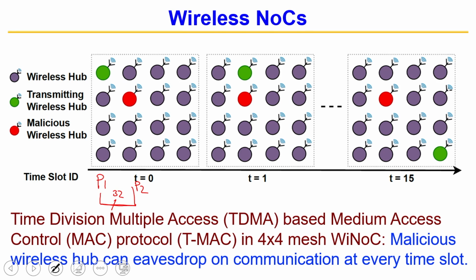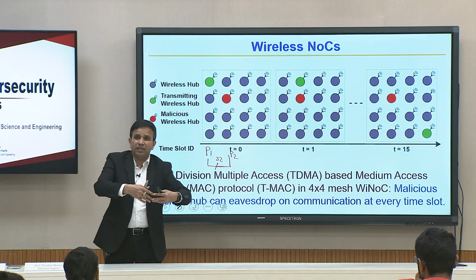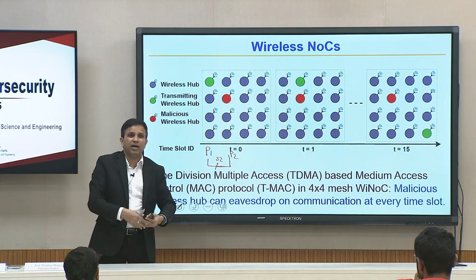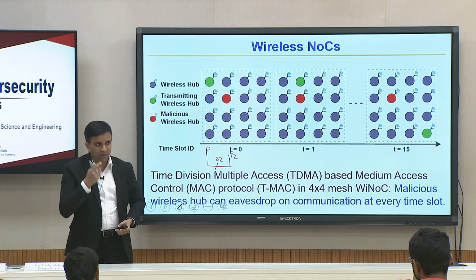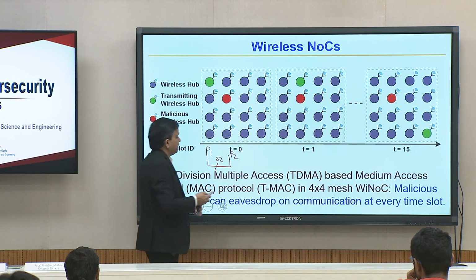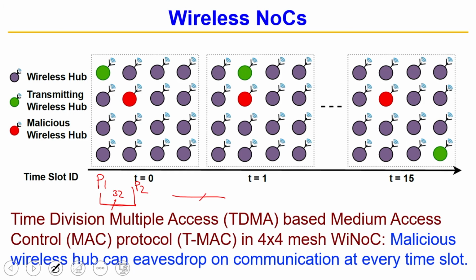Two people cannot do that, only one can do at a time, because if two people try doing it, somebody wrote 0, somebody wrote 5, you do not know what value will come out of it. It does not have to be even 32 bit, it can be just 1 bit line. If one person is writing 0, another person is writing 1, and you ask what is the result in that, it is non deterministic. In hardware community, you call it tri-state.